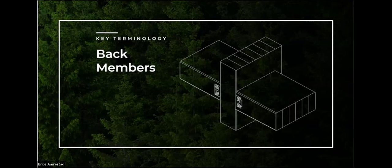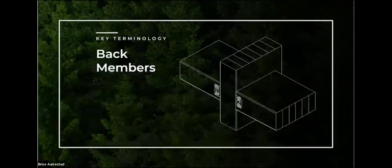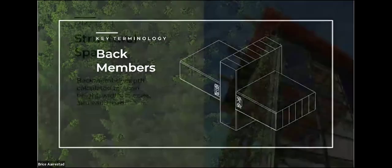In a timber curtain wall, we replace what is traditionally this aluminum back member and use an engineered wood. I'll go into how that wood is constructed and the requirements of that a little bit later in the presentation, but just want to throw that out there. Key piece of terminology there: back members as the structural components and the timber components in a timber curtain wall.